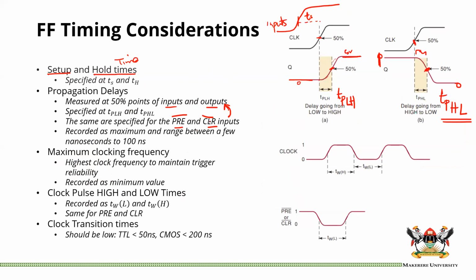Now, obviously, these ICs, these flip-flops, will have different transition times or hold times and so on. And so when it comes to times, they will have a batch of, say, 1 million of them and test them, and they will have different times, but they will record the highest time. The one that records the highest time becomes the highest time for all of the flip-flops. Even if these flip-flops are by the same manufacturer, same type, same model number, and so on, they will have differences in operation. Some will respond faster than others.